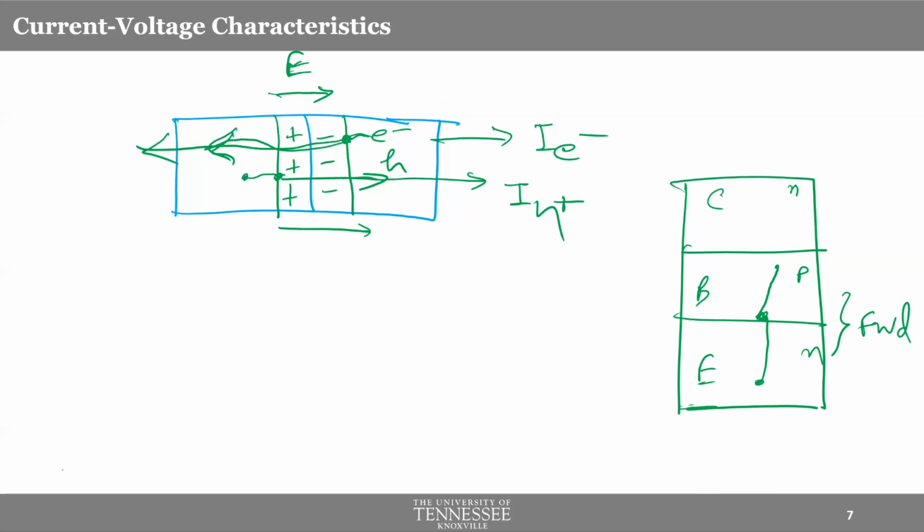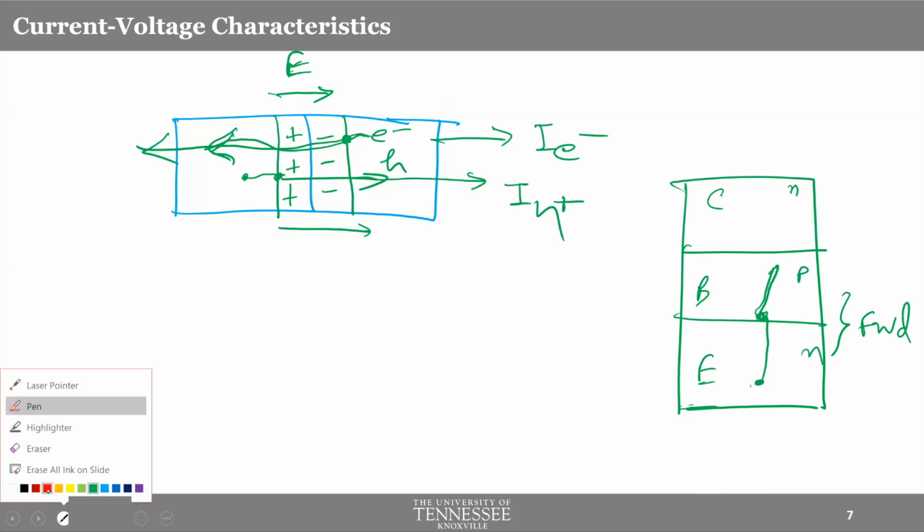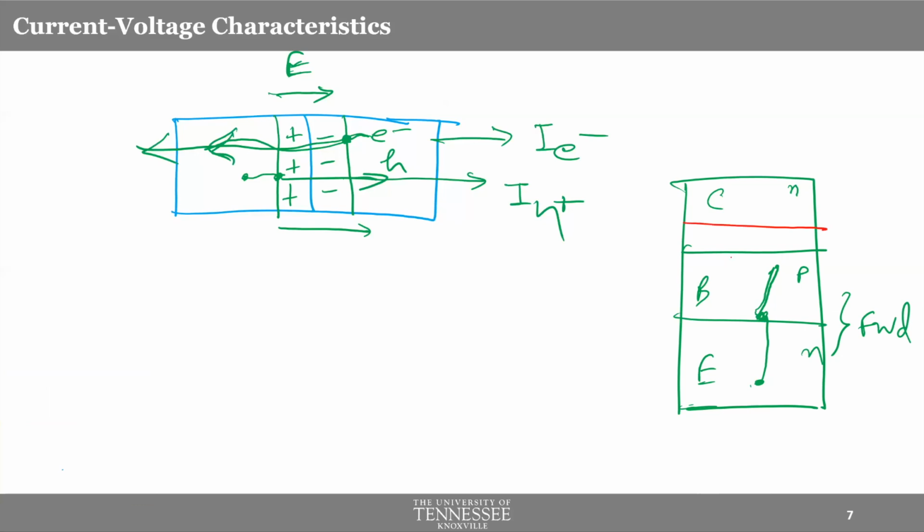Flows of electrons and holes are permitted. So electrons will flow from the emitter to the base and try to diffuse all the way towards the collector. Now here is where the action happens: near the collector you have a depletion layer, and let's try to find out the direction of the electric field.